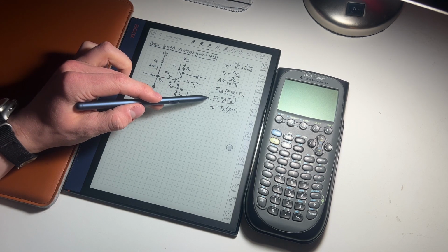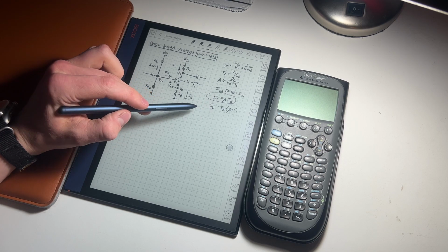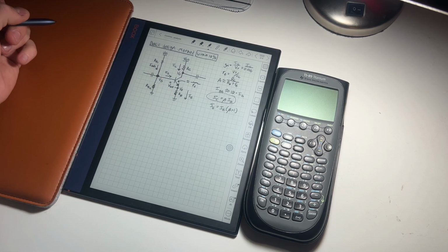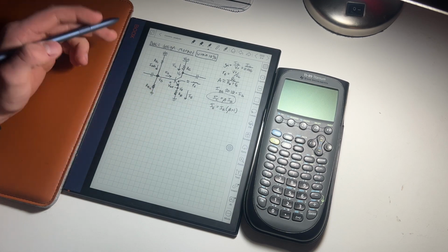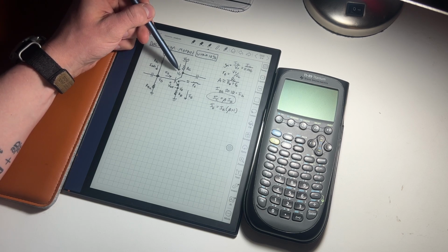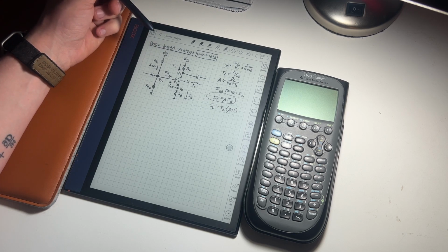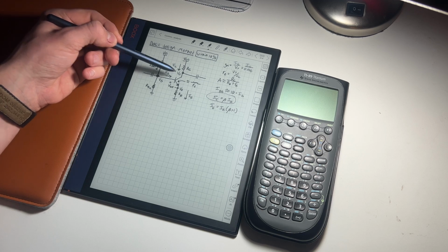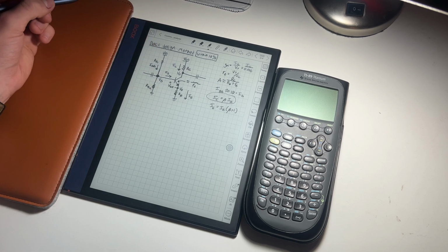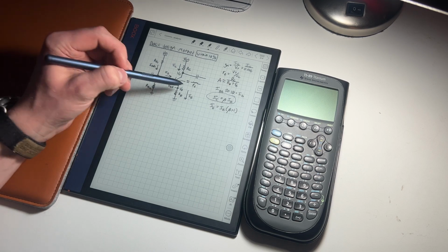Lastly, this last equation here, IE equals IB times (beta plus 1). Where did I get that? Well, if you look here, you have IC running into the collector of the transistor, and you have IB running into the base of the transistor. So those currents have to go somewhere. And where do they go? IE.